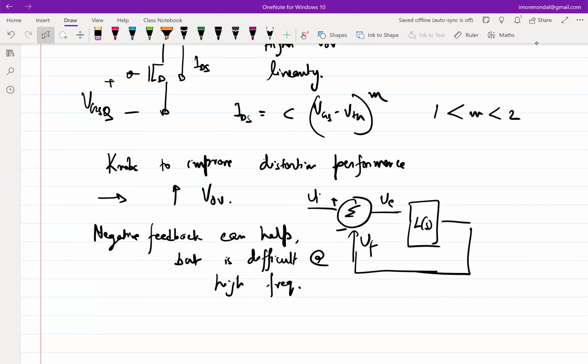Between getting to oscillator and being perfectly stable, there is a whole bunch of phase lag possible between 0 and 180. It is going towards instability if the phase lag at around UGB is getting closer to 180 degrees, but need not necessarily be. But what I meant by this is that let's say you have designed a loop which is stable, right?